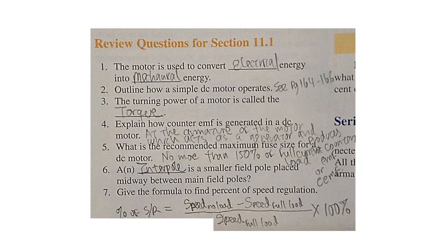So basically, DC power or voltage is channeled through the brushes into the commutator, which is a device that has two parts completely isolated from each other, which conduct electricity.